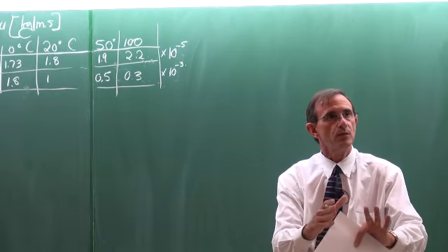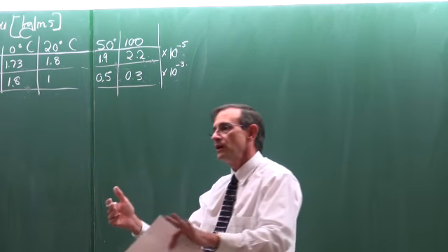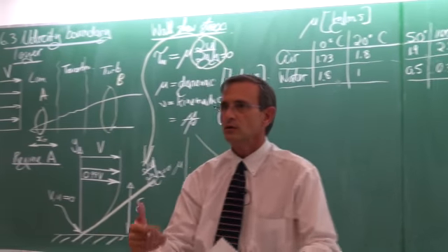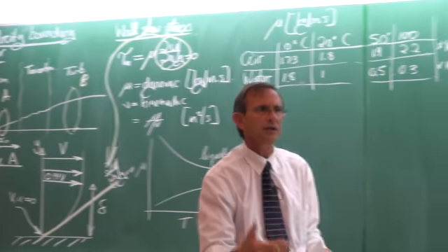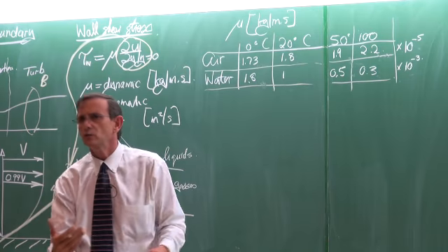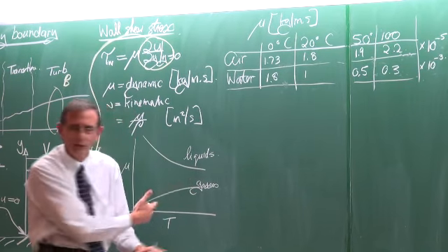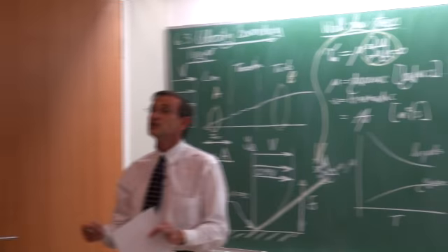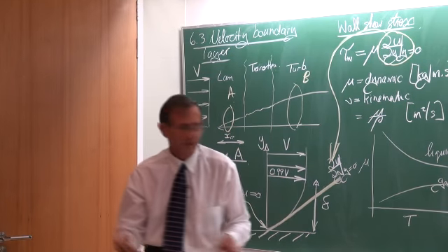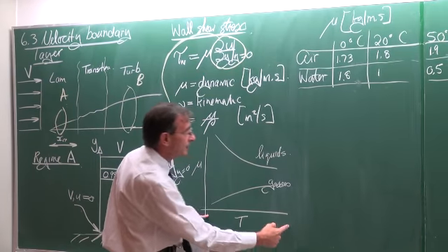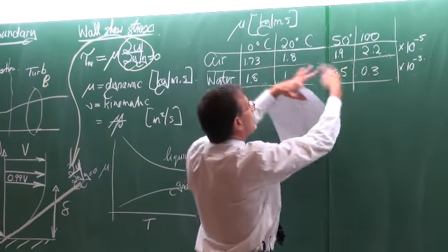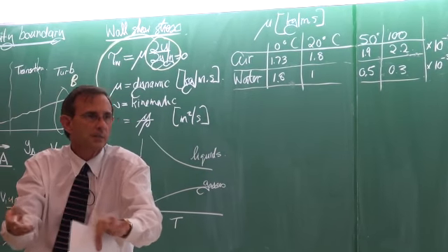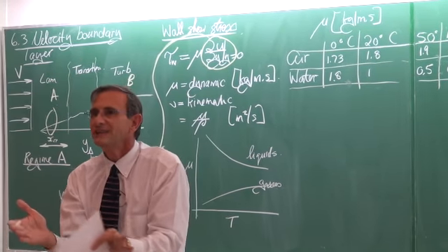However, and that is very important, in many cases we are going to make the assumptions that something like the viscosity is a constant, the thermal conductivity, and the Cp, etc. So the question would now be, but how can you assume that? Obviously you can see it is a function of temperature. The answer is, it's not a strong function of temperature. This is a huge scale. If we look at typical temperatures where heat transfer occurs, a heat exchanger typically, delta T's of about 10 degrees.